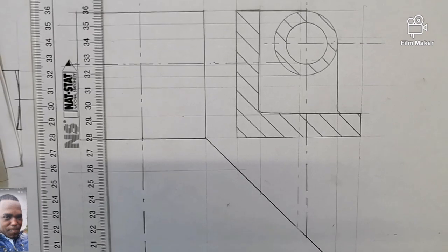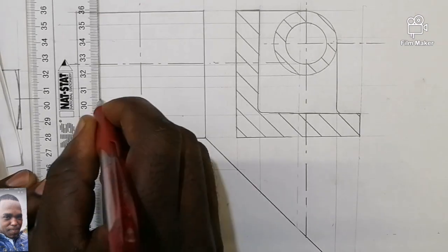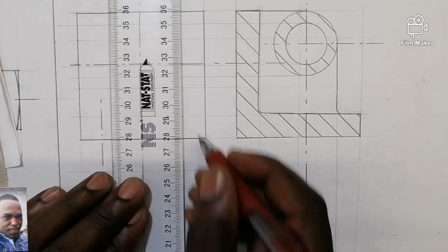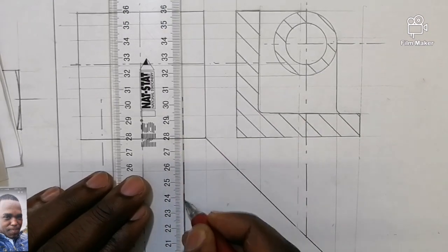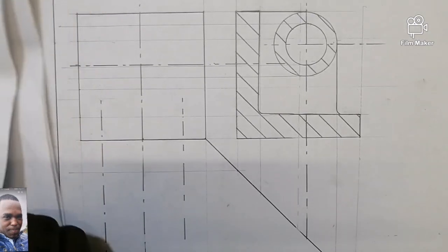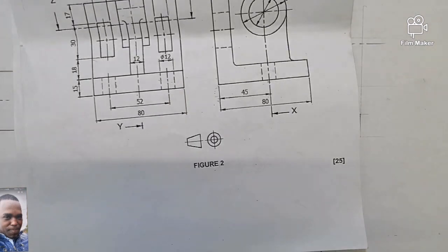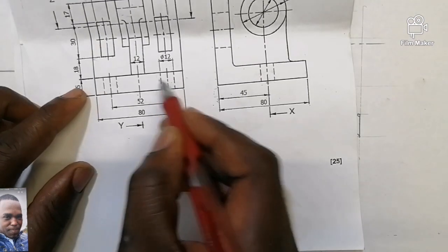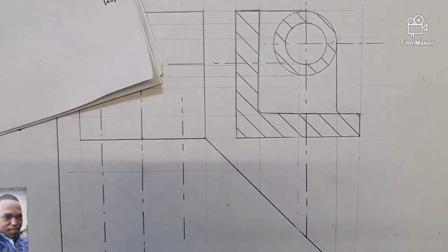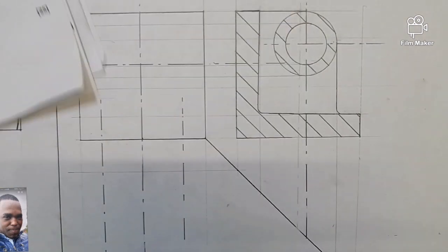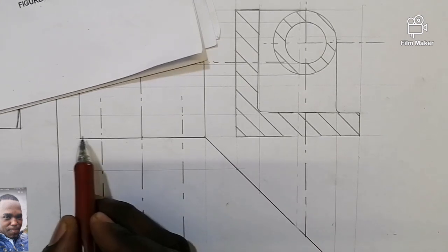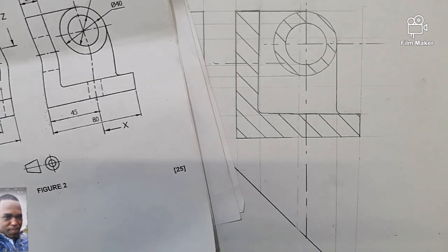And these two are giving us the centers of these holes, and draw them down, because you are still going to need these centers when you are drawing your top view. Project them down like this. Their diameters, diameter what? Diameter 12. At the moment, I don't want to say 12 divided by 2, so that we end up being accurate. Let's see what is left, because now I don't want to say 6 millimeter, because I might end up not being accurate.